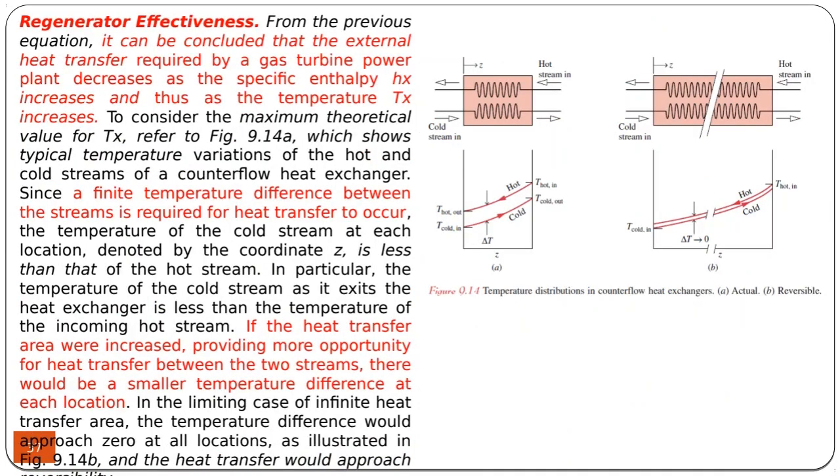Of course, the regenerator cannot transfer all the waste heat to the first part of the cycle, because in order to utilize all the waste heat, it's necessary to have an infinitely large surface heat exchanger, which is not so practical. A typical or practical heat exchanger would have a surface area of a limited value.